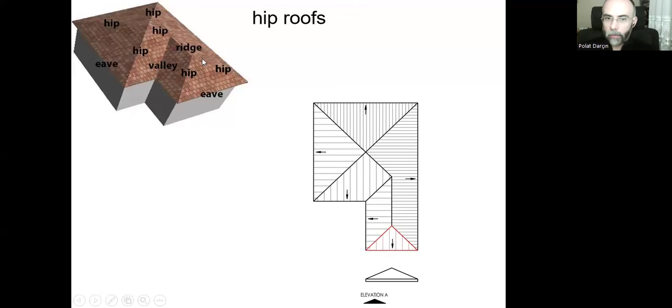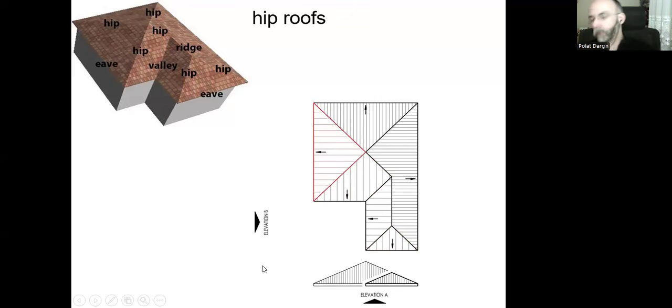Now you can see it in a better way. That's the first part, this red part, and that's the other part. As you can see, I just leave a small gap, and there's a little line weight difference in order to indicate that the viewer can understand this surface is closer to us, this is slightly further away, and we can have the hatch with the same gap, and we can draw this elevation.